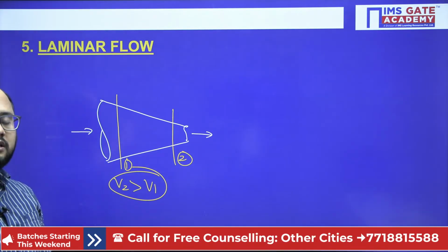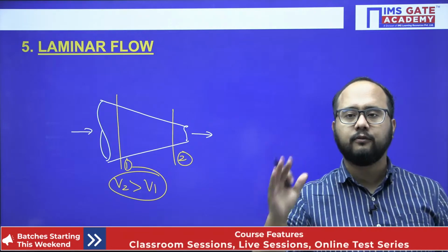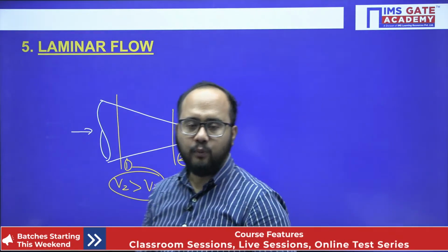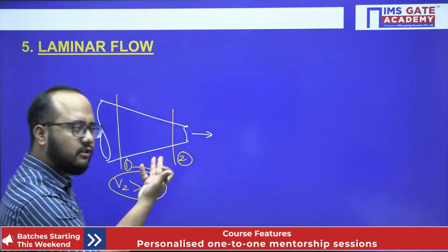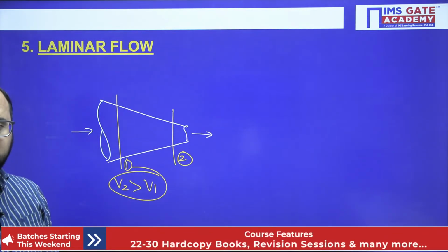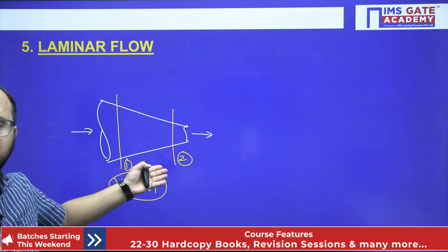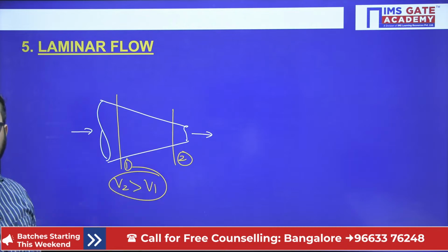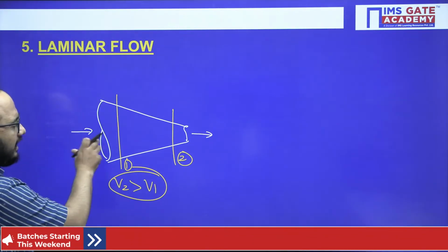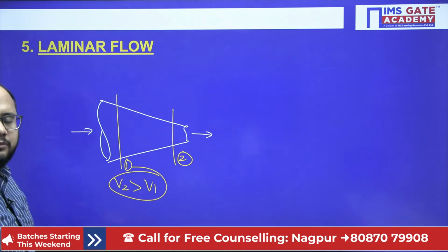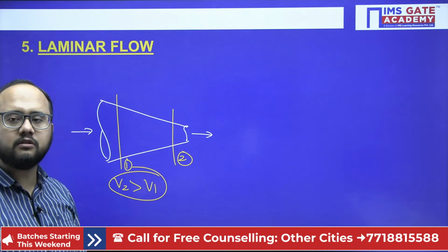Now, as you are asking about steady flow, most of our engineering devices come under steady flow. You are asking about steady plus non-uniform flow, so I can give you this example. If you consider any particular time, the value remains fixed. Let's suppose this is a nozzle installed in a hydraulic power plant or a steam power plant. If the values at the entry are fixed with respect to time, it becomes a steady flow, and obviously, as it passes through the nozzle, it becomes a non-uniform flow. So it is an example of steady plus non-uniform flow.